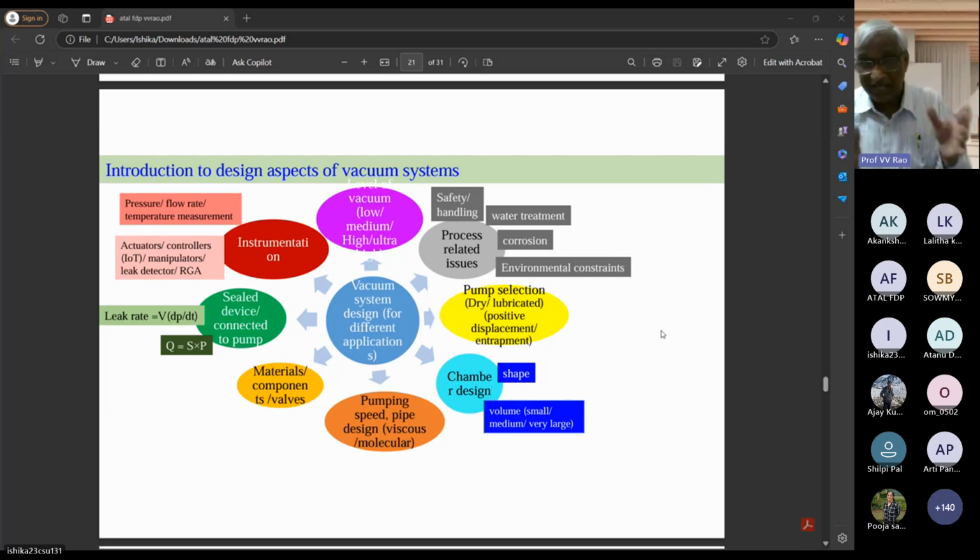That means you degas it intentionally to remove all the junk, and then during the actual application you have a clean atmosphere. Clean means vacuum is clean, no doubt, but ultra high vacuum is ultra clean. Semiconductor is ultra clean. Whereas in vacuum technology for, say, the chemical industry, 99.9% removal is also not small, and that's enough for them. But here you have to do 99.99999%.